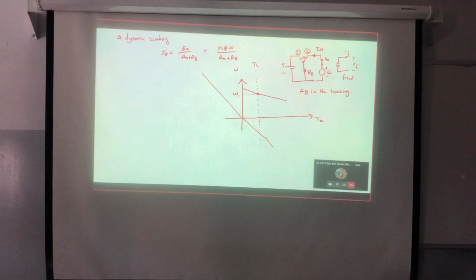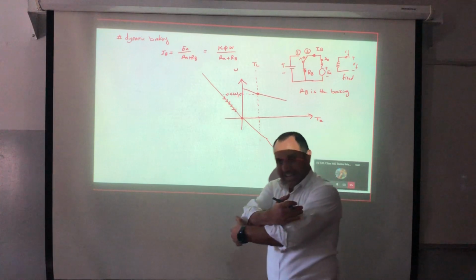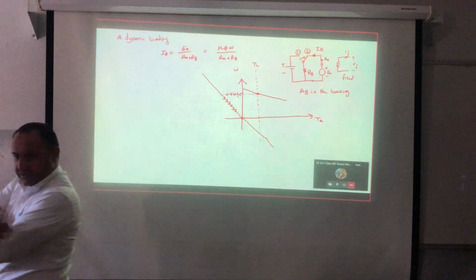In the first stage, this torque speed characteristic now is forbidden. The machine will go to the new torque speed characteristic, entering Q2, which is the regenerative braking. Then it will start to decelerate until crossing 0. Now, at this point, if I engage a mechanical drum, the machine will stop, yes or no?